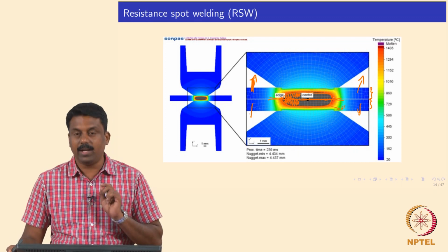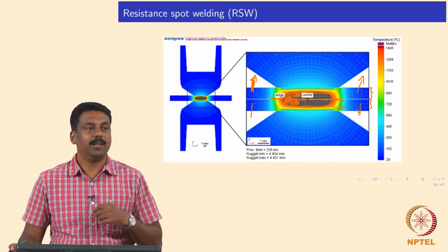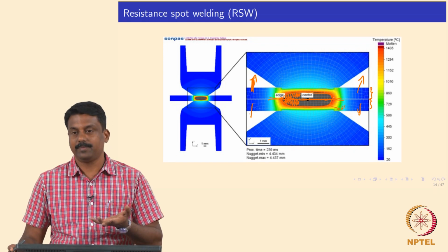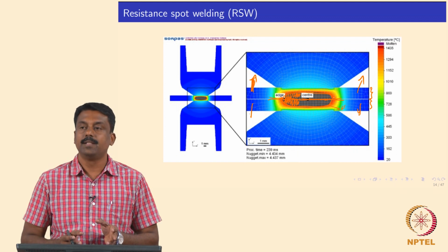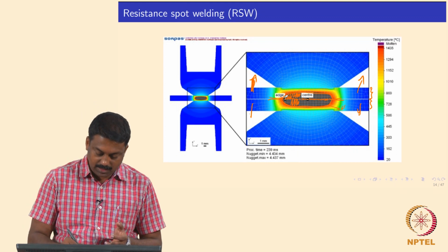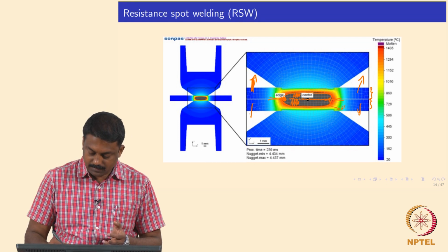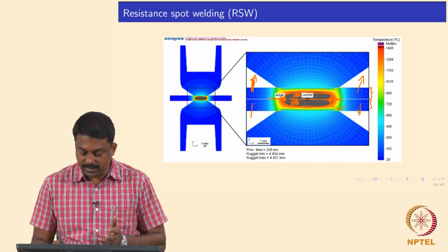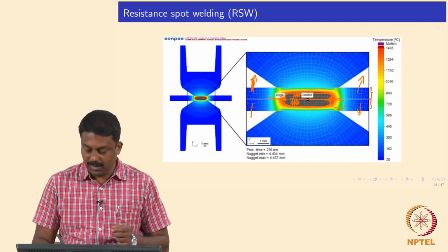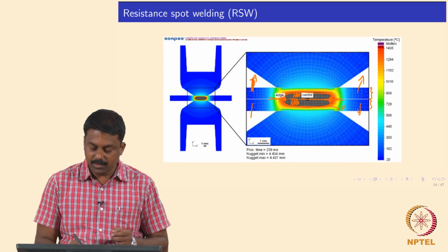So, now the trick is to avoid such a failure. That is why we use post weld thermal cycles, so that we can homogenize or change the microstructure in these regions, so that we arrest the crack propagation from the edge of the fusion boundary to the weld center.